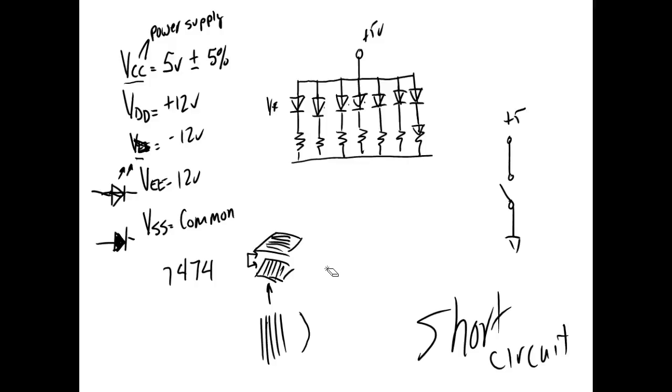So when we look at our lab, you're going to be required to do some stuff. I've got the circuit wired up, but y'all still got to do some stuff in here. So what do you got to do here? Yeah, you got to do the pinouts of these ICs, right? And we're doing a 74147, which is an encoder, and a 7447, which is a decoder. Okay, where are you going to get that information at?